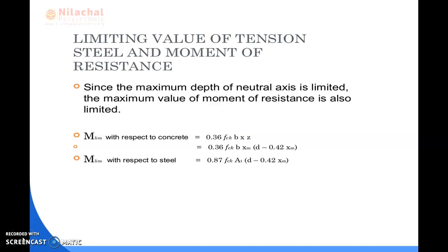Good morning everyone. In the previous class we discussed the maximum depth of neutral axis. In this class we discuss the limiting value of tension steel and moment of resistance. Since the maximum depth of neutral axis is limited, the maximum value of moment of resistance is also limited.